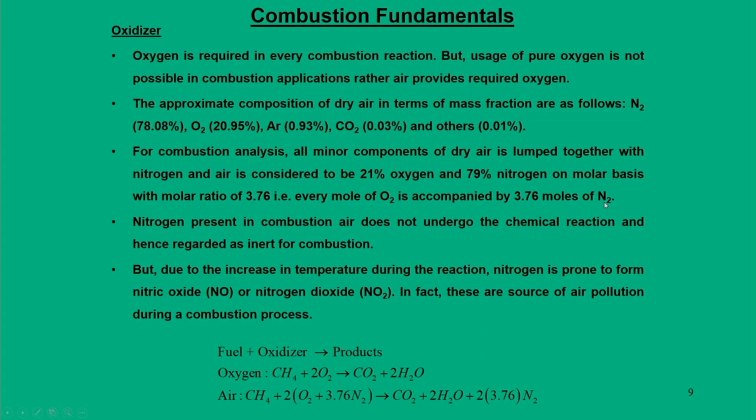Although nitrogen gas is present in the chemical reactions, the nitrogen becomes inert. That means nitrogen has no role during the combustion process. In a complete combustion process, all the fuel should burn, that means carbon should come to carbon dioxide and hydrogen should come to water. So, in a complete combustion process we will get CO2 and water.